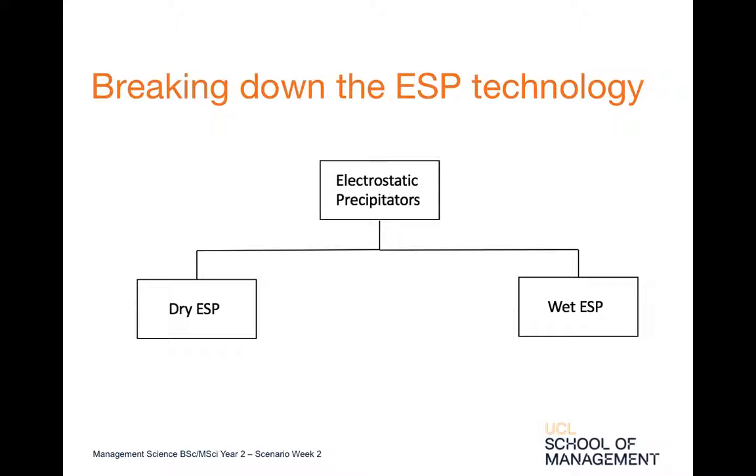Electrostatic precipitators are generally divided into 2 broad groups, dry ESPs and wet ESPs. The distinction is based on what method is used to remove particulate from the collection electrode. Dry ESPs remove dust from the collection electrodes by vibrating the electrode through the use of rappers. A wet electrostatic precipitator operates with water vapor saturated air streams. The wet ESP is commonly used where the gases are high in moisture content, contain combustible particulate, or have particles that are sticky in nature.